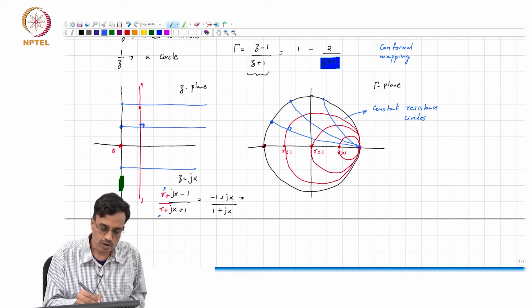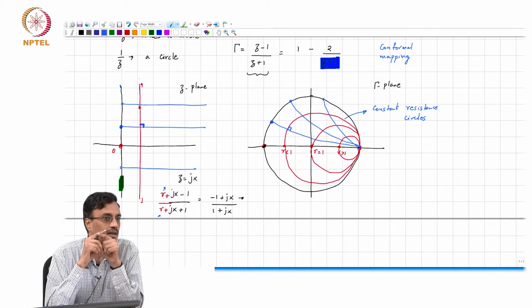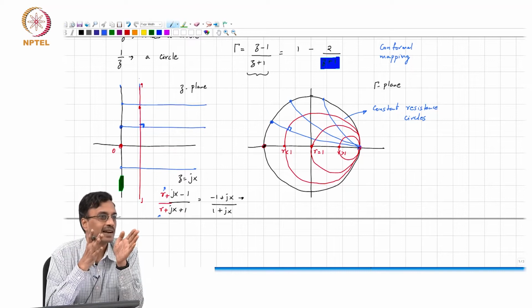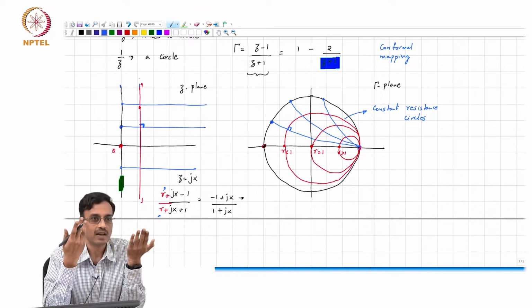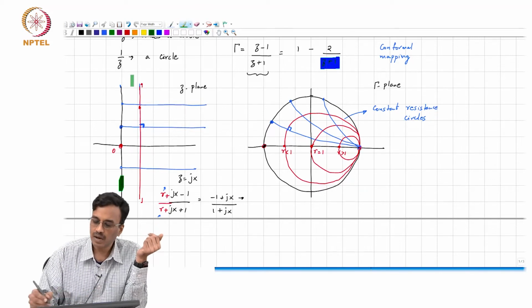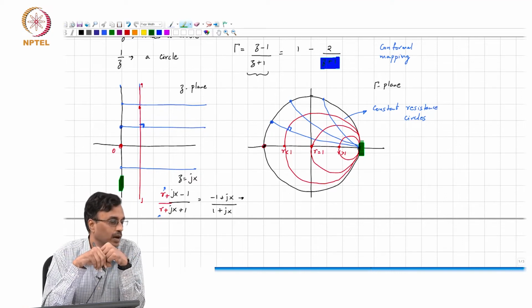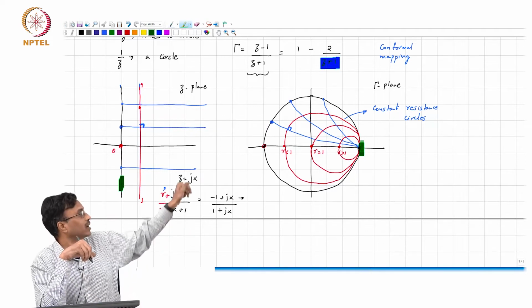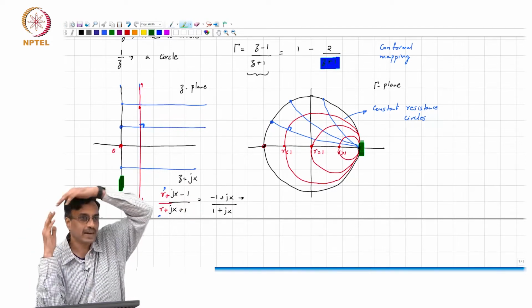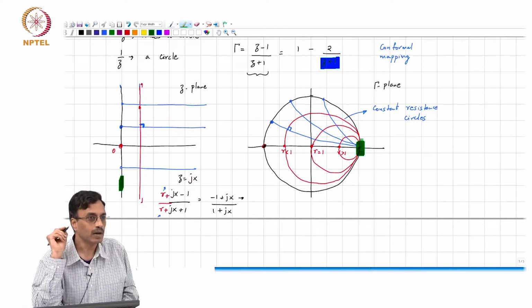And remember, these 2 points in the z plane, where do they meet? Where do the two parallel straight lines meet, folks? Infinity, right? And so they meet at a point. The infinity in the z plane maps onto +1 in the gamma plane. So all these vertical lines and all the horizontal lines all meet at infinity, so they all basically meet at +1.